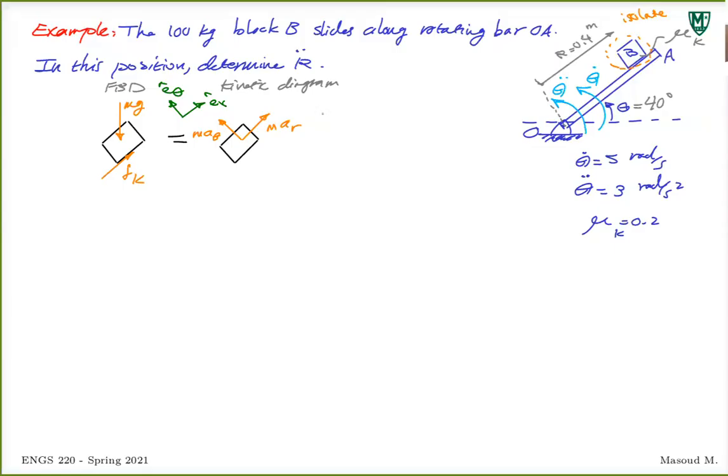Normal force, and remember, normal force is always perpendicular to the surface that the object is in contact with, right? So that means this would be my normal force. I'll just call it N. All right, so that's all we needed. That's pretty much all the forces. Kinetic diagram is pretty straightforward. Multiply mass with the components of acceleration you have in that specific coordinate system.